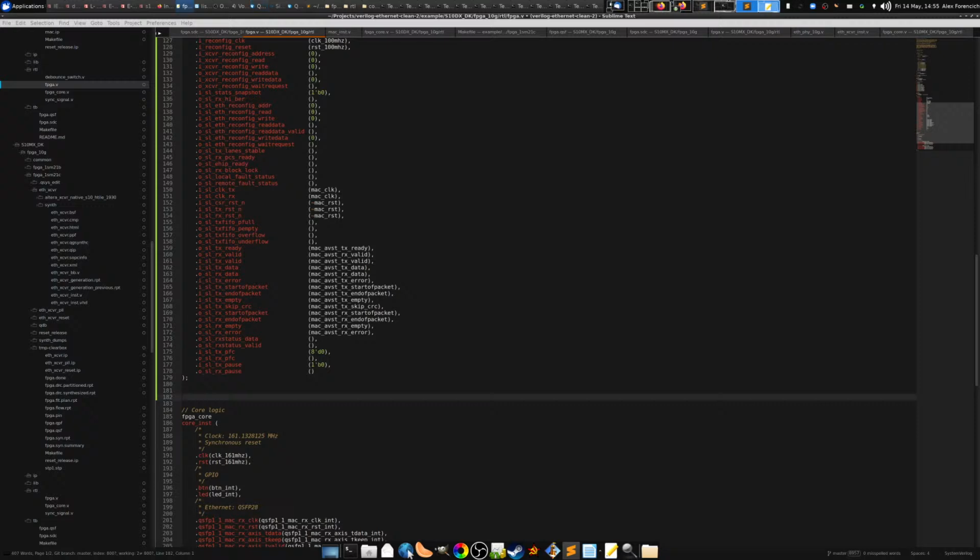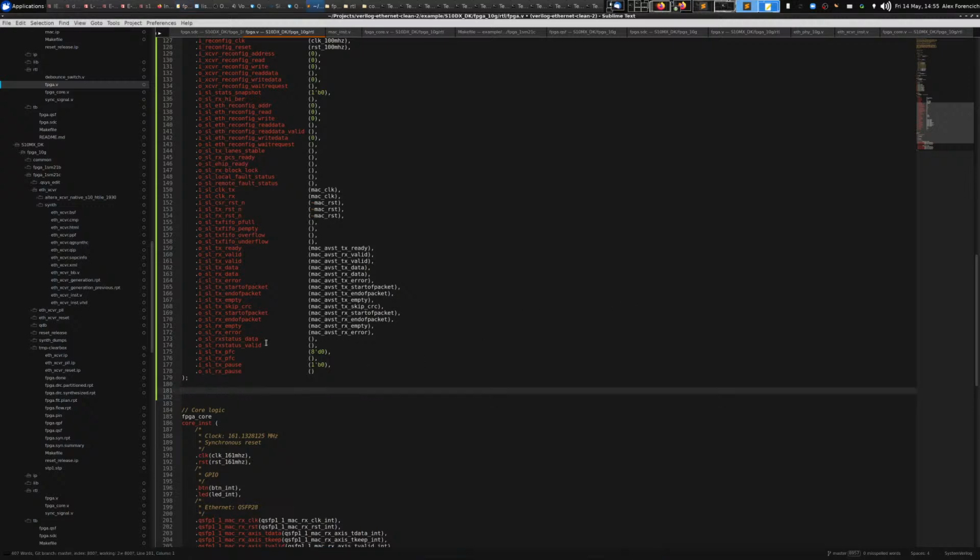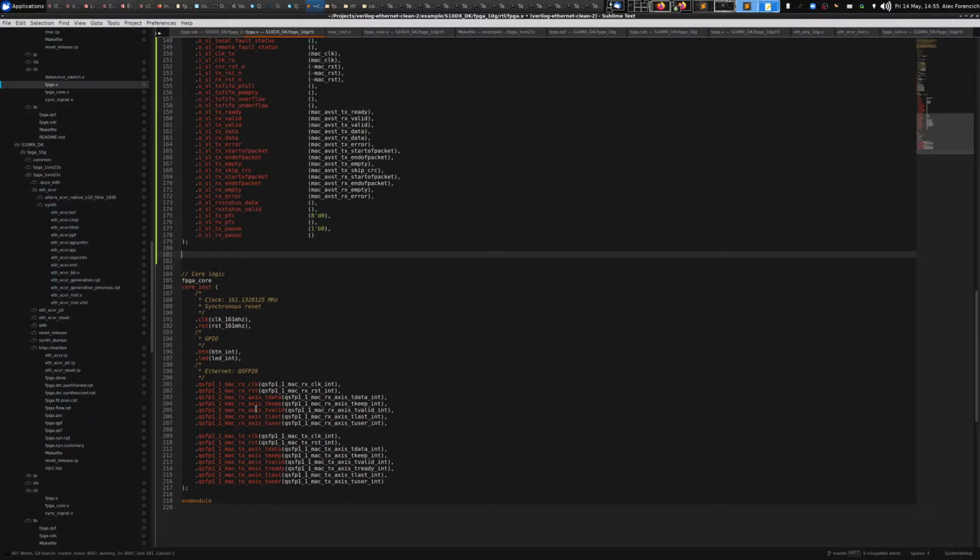Okay. All right, so the next thing I need to do is put together some real simple logic to adapt this to AXI. And there's 2 things I need to do primarily. One of them is I need to reverse the bit order. I need to flip-flop between the empty and the T-keep signals, and then I need to regenerate the start of frame signal for the transmit direction. So that's not particularly complicated. So let's take a look at this here.